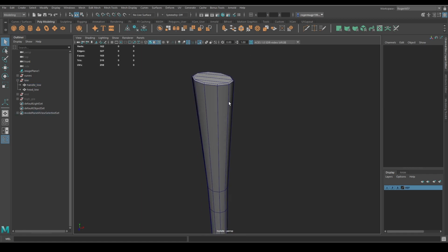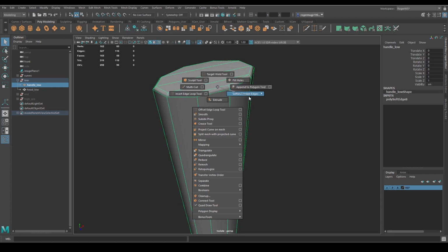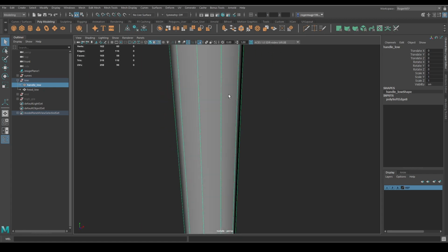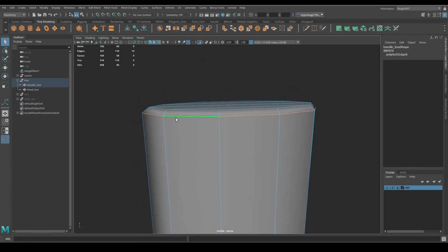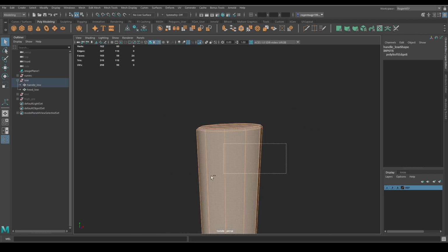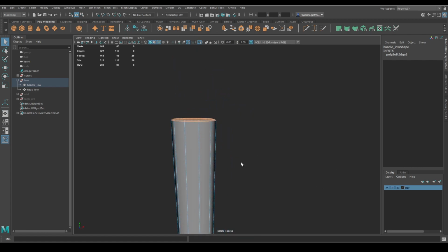Oh no, for example, this, I'll show you. If you remember correctly, I did a soften on every edge. And so if you see, if I toggle the display for the edges, everything is dotted. So here, like I said, every hard edge needs to be a UV cut, but not every soft edge needs to be a UV cut, but you can cut it, you know? For example, if I cut all the way here, it's fine, and I don't need to turn it into a hard edge. It doesn't matter. I can cut here because I'm gonna make this a separate UV shell, and you'll see, and then this one another UV shell, and the middle part is gonna be a separate flat shell for the UVs.